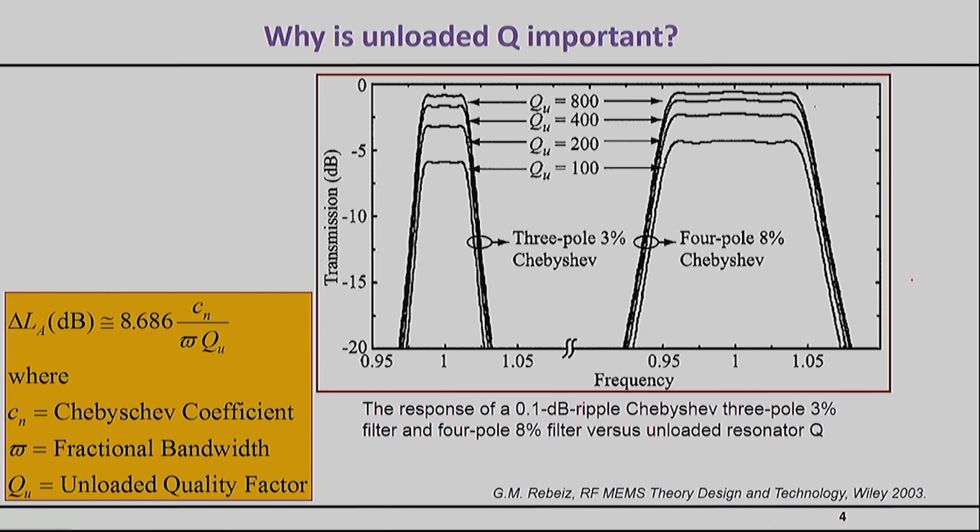So the most important thing that you will notice is the insertion loss of your filter. The insertion loss is basically the loss that you will have in the passband of the filter. What is really important to keep in mind here is that the worse your quality factor is for the resonator, the worse the insertion loss will become. So these are two interesting cases.